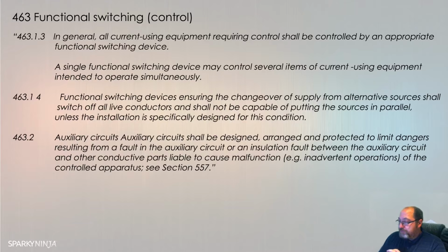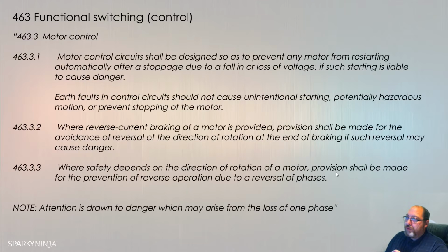Motor control. Motor control circuits will be designed so as to prevent any motor from restarting automatically after a stoppage due to a fall in or loss in the voltage, if such starting is liable to cause danger. We mentioned in the previous video about undervoltage protection.